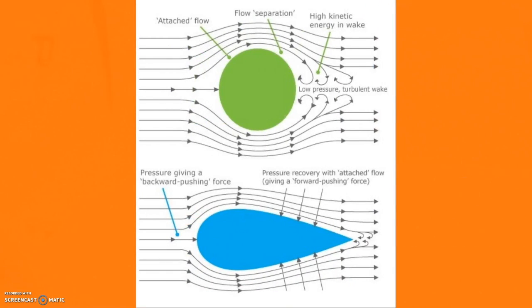In this visual, you can see the difference in pressures of an object depending on its shape. The less flow separation that occurs on the shape of an object, the lower the drag differential is between the front and back of the body. Essentially, the lower the pressure differential correlates to a lower drag force. As we can see, the least amount of separation occurs on the airfoil. However, it's not feasible to change the shape of a golf ball for this reason.